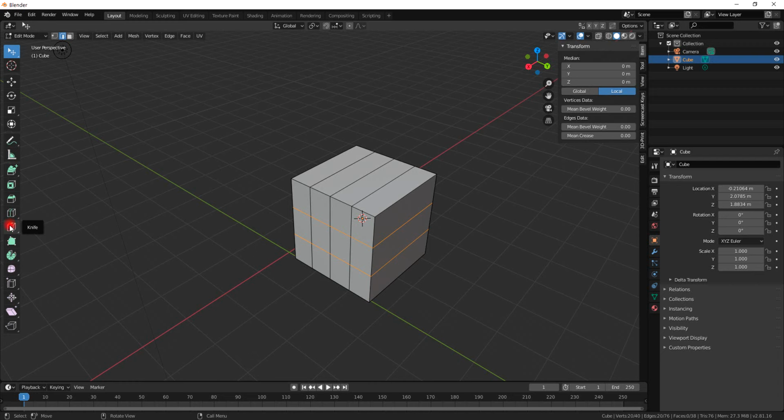This one here is a knife tool. A knife is nice for getting vertices into your mesh. Let's say that I wanted to have this one cut into with a small square right here. I will just go in here, click on the knife, and pull across the edges that I want to have, and then right click to left click to pull them out, and then enter to confirm them. I'll put the next one there, like so, and like so.